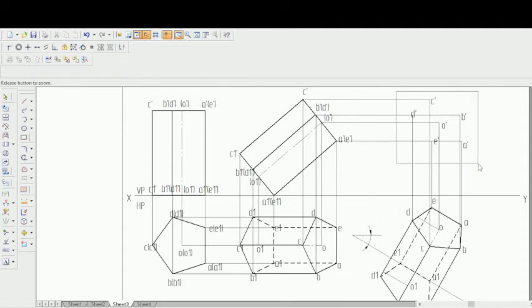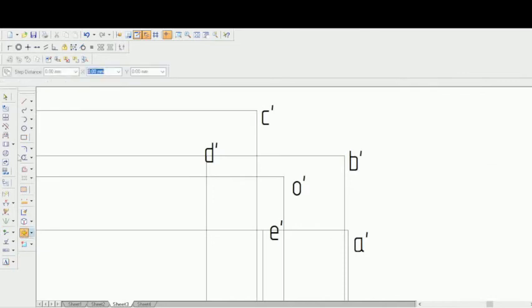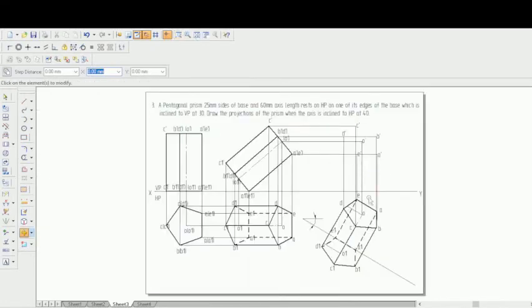Now go to zoom and position it correctly. Go to move, you can see that the copy is switched off. So you can position it correctly, a little closer to that point. Now you can fit it. Now you can see all these points are placed correctly: A to A dash, B to B dash, C to C dash, D to D dash, E to E dash. When it is placed correctly, it will be much easier for you to draw those points. That is the reason.